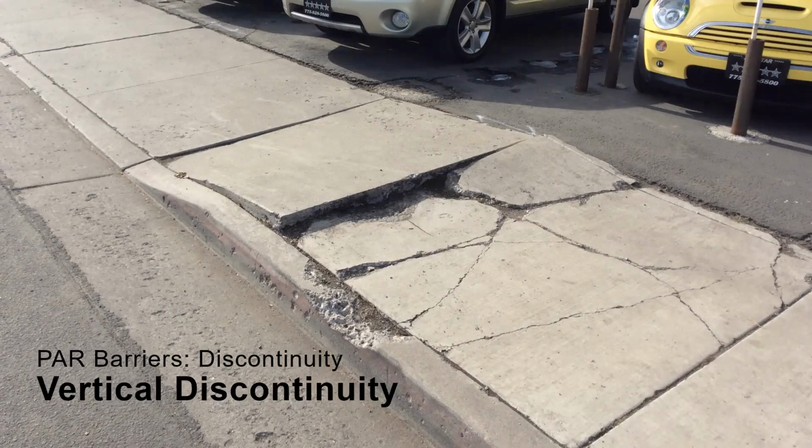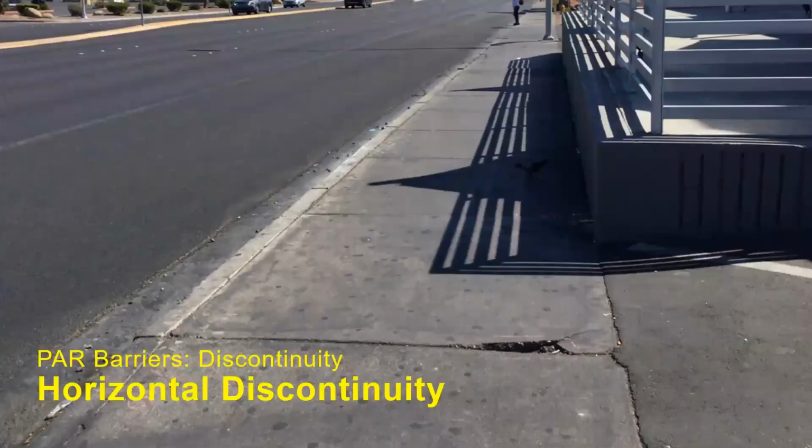Tripping hazards, such as vertical discontinuities, as shown in this picture, are also collected. Every vertical change in level greater than a quarter inch must be beveled with a maximum slope of 50% up to a maximum height of a half an inch. Anything above this is a potential tripping hazard. Horizontal discontinuities are openings in which a cane, a foot, or a caster may lodge and cause tripping or tipping. Any opening that measures greater than a half inch for length, width, and depth is considered a potential hazard.